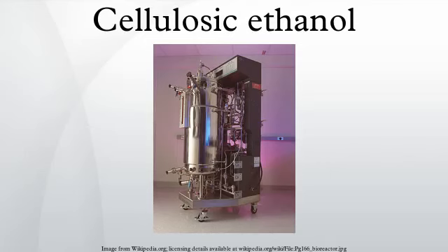Pre-treatment. Although lignocellulose is the most abundant plant material resource, its usability is curtailed by its rigid structure. As a result, an effective pretreatment is needed to liberate the cellulose from the lignin seal and its crystalline structure so as to render it accessible for a subsequent hydrolysis step. By far, most pretreatments are done through physical or chemical means. To achieve higher efficiency, both physical and chemical pretreatments are required. Physical pretreatment is often called size reduction to reduce biomass physical size. Chemical pretreatment is to remove chemical barriers so the enzymes can have access to cellulose for microbial destruction.